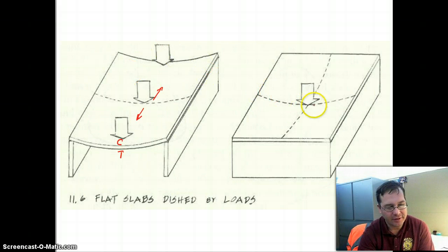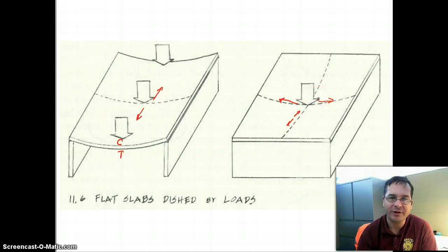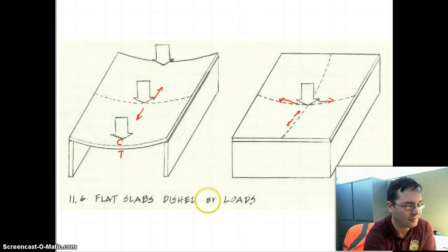Compare that to this non-developable shape here in this slab. So you see that this is concave in multiple directions. So here now there is tension along this direction of the slab, as well as tension along this direction. Excuse me, I'm sorry. There is compression on the top of the slab. There's tension on the bottom of the slab. In those directions, which means that, again, you're getting more strength out of the slab because you're using more of the molecular bond's ability to resist the force.